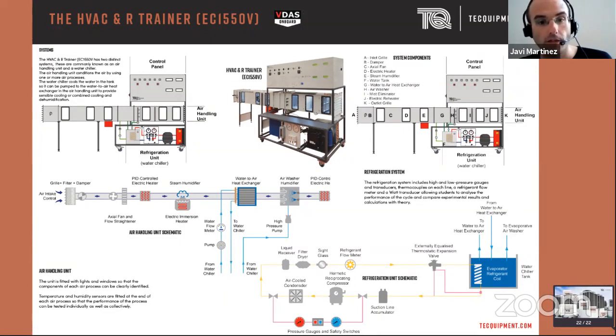And then at this point, we've got hot and humid air, which is what you will normally get in a country like, for example, Malaysia. And then we can cool down the air via the dry cooler, the water to air heat exchanger, or the air washer humidifier. And we can monitor and control the process in different ways.